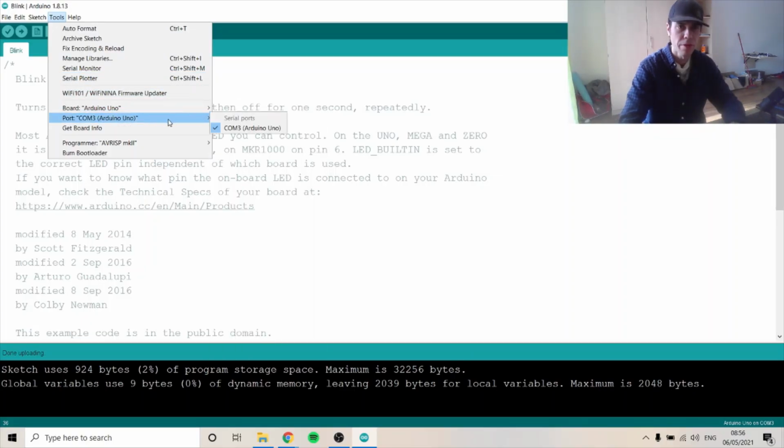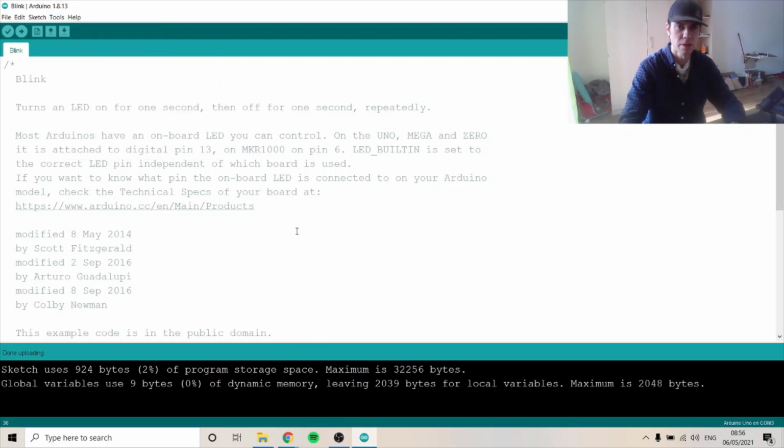Another thing that you need to do is pick your Arduino Uno, it's the one I use, and then in the port you pick, when it's plugged in, it won't automatically be picked. So then you pick this, and then it's able to load the code.